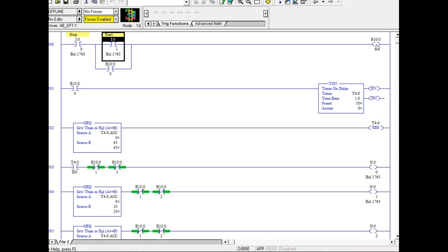That's a bit file. I don't need that. Of course, this is an internal coil right here. This is an output, right? By the way, you can put comments and symbols all day long. But if you upload your program from a PLC, there's no symbols. So when you download it to the PLC, you don't download the symbols. Right? You understand? So if you upload that program back into your computer, there's not going to be any symbols